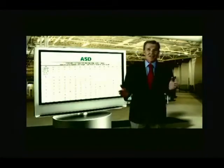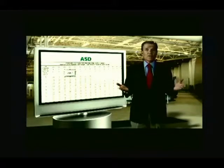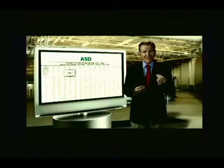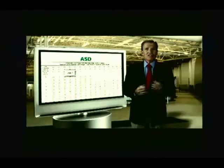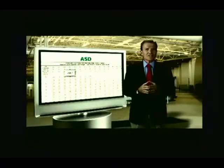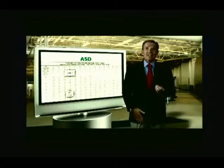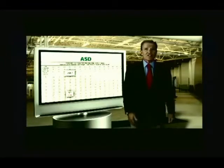Standardization is another key advantage. When a joist is specified, a 24 K7 for instance, simply the recording of that designation automatically embodies all of the specification and load table requirements for that joist. The joist will carry the load as called for in the load table. It will have a standard 2.5-inch end depth.